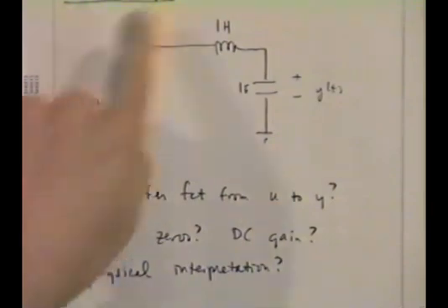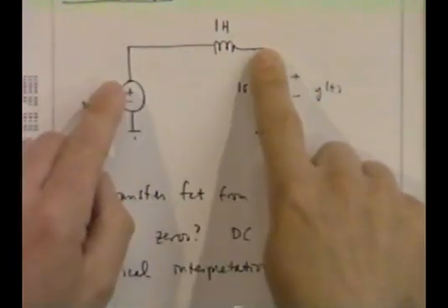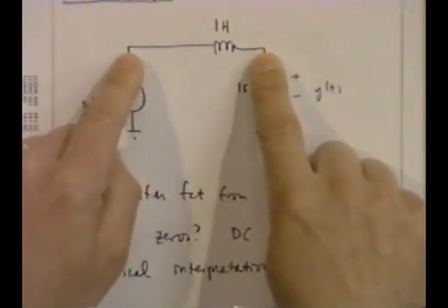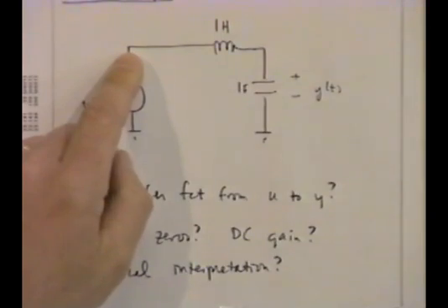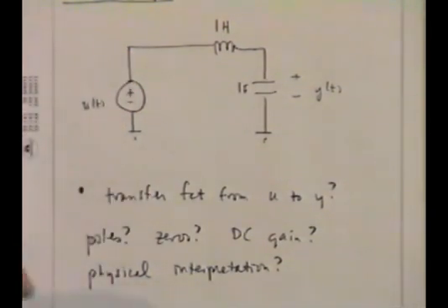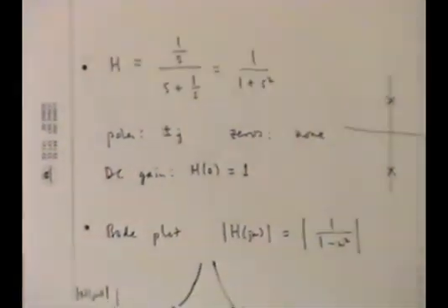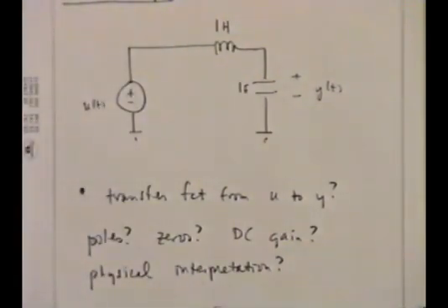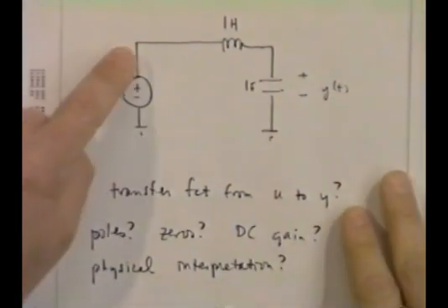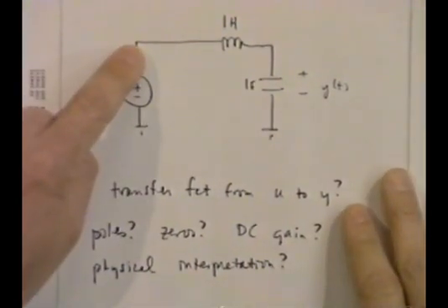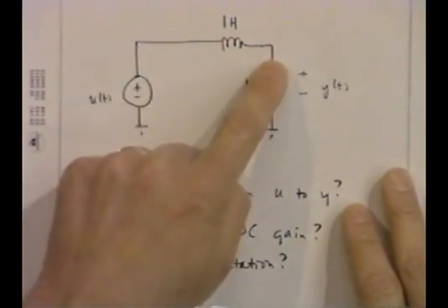So how this thing could work out, that this signal would be in phase with that signal, is very interesting. Actually, it works because it's a ratio of imaginary to imaginary. That's pure imaginary, and the ratio is real. And in fact, you can make some sense of that. If I put in a sinusoid here at a low frequency, this signal here is also a sinusoid, exactly in phase.